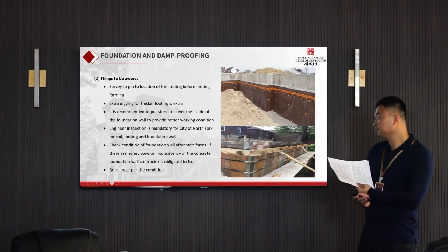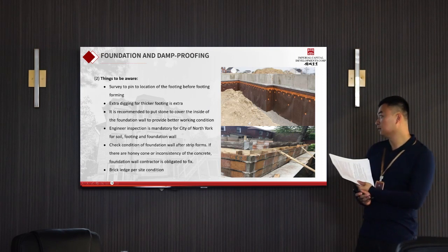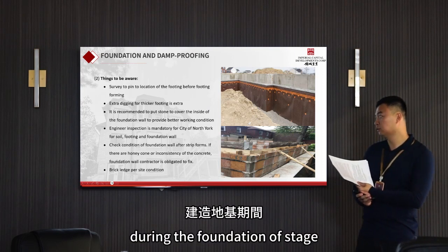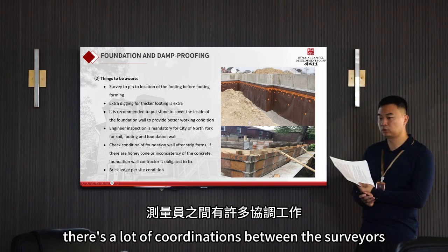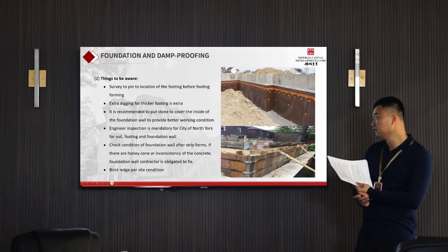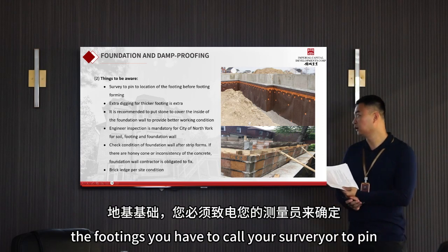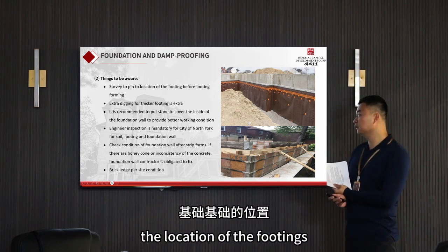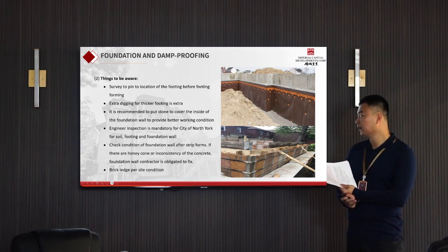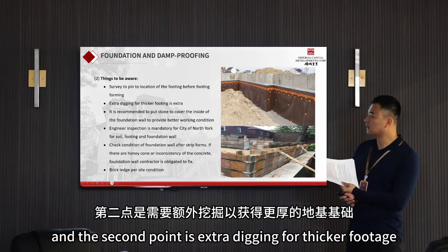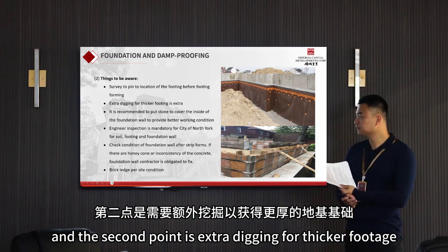Things to beware. During the foundation wall stage, there's a lot of coordination with the surveyors. So even before you do anything to form the footings, you have to call your surveyor to pin the location of the footings. And the second point is extra digging for thicker footings.